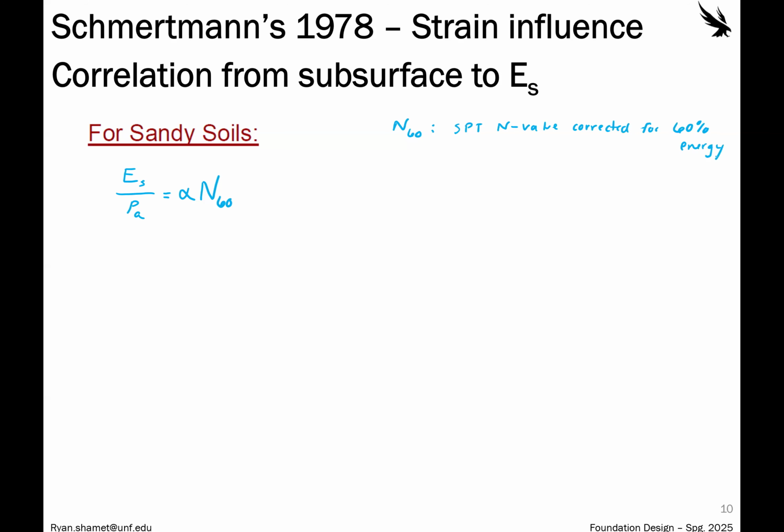And so we went through a whole process. It's based off of what we covered in Geotech 1, so go back and look through those notes in your Geo 1 class, or you can look up ways to calculate the N60 value. It's based off of the drill depth and the diameter. It's a normalization technique for N60.